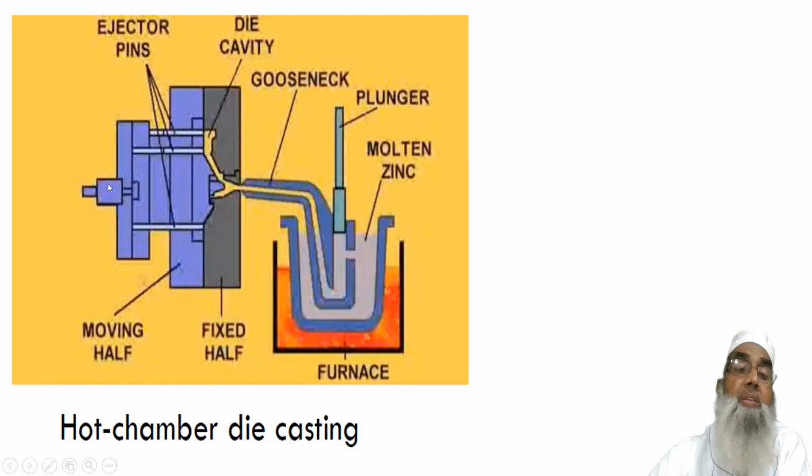In hot chamber, the chamber of the molten metal is dipped in the furnace itself, and the plunger is dipped in the molten metal. When the plunger moves down, it pushes the molten metal and injects it through the nozzle into the die cavity.